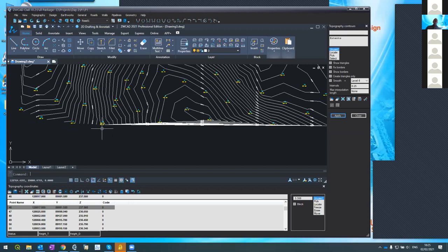In this case, let's say the distance between here, just for my example, let me remove the object snap. From here to here was 28 meters, which makes sense. So if this is 28 meters, this is 20, this is 30 meters, 70 meters will define abnormals. Can do it 50 even. So I'm telling the system, if the distance between 2 points is longer than 70 meters, do not interpolate between them. Do not create contours between them. I can do it even 60.